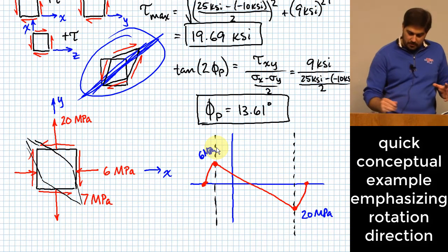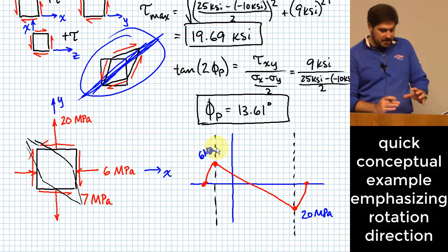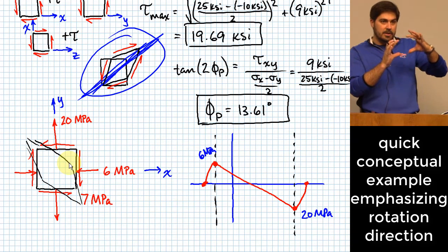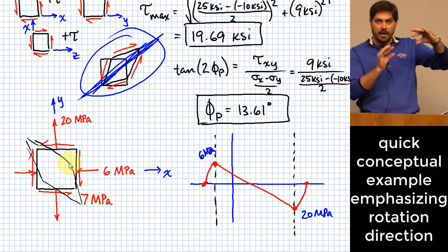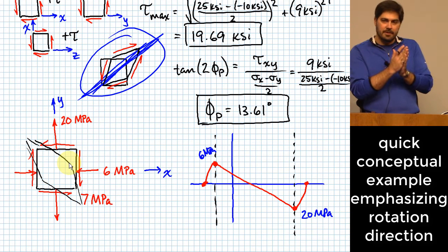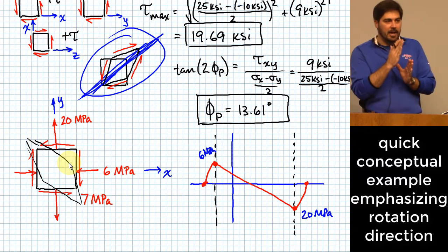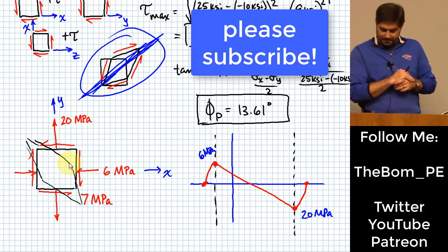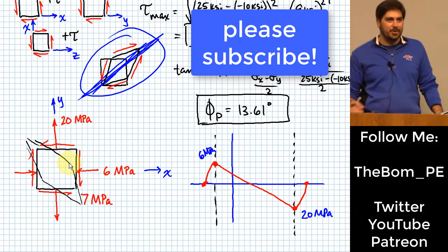So basically what I'm saying is, if you think about this rationally and think about what direction the shearing stress would skew the element, that gives you a clue as to the direction you would have to go rotationally to get to the coordinate axis where you would have a principal stress. Maybe that's given you at least something to think about.